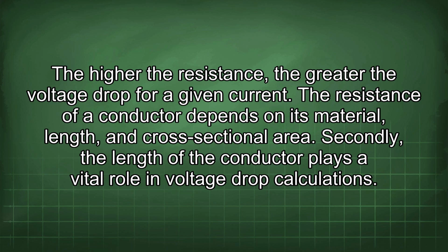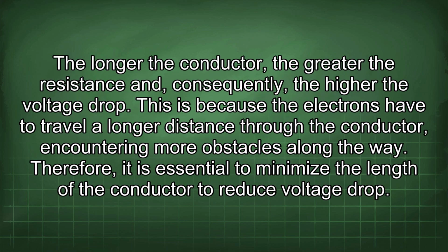Secondly, the length of the conductor plays a vital role in voltage drop calculations. The longer the conductor, the greater the resistance and, consequently, the higher the voltage drop. This is because the electrons have to travel a longer distance through the conductor, encountering more obstacles along the way. Therefore, it is essential to minimize the length of the conductor to reduce voltage drop.